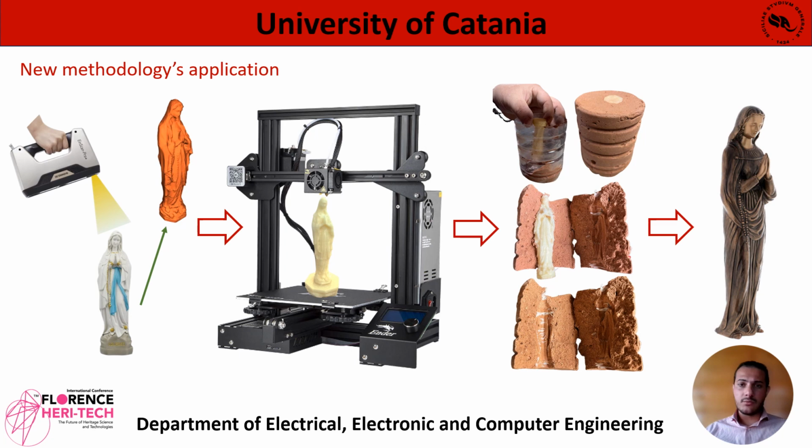Once the refractory was hardened, it was immersed in a tank full of water at room temperature for about 3 hours to completely melt the prototype PVA. Finally, the refractory was fired at a temperature of 900 degrees centigrade to remove any residue, and once it came out from the furnace, the molten bronze was poured, resulting in the final result.